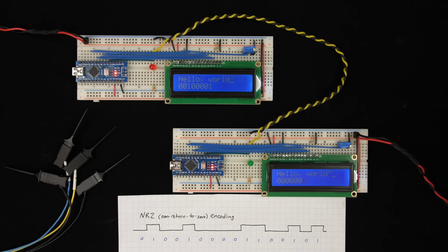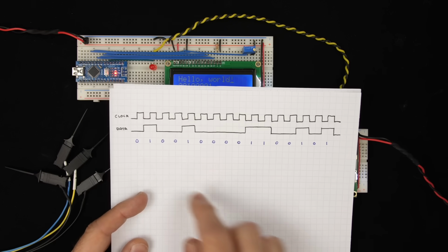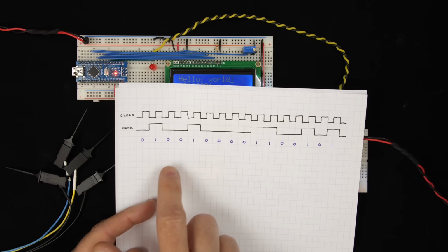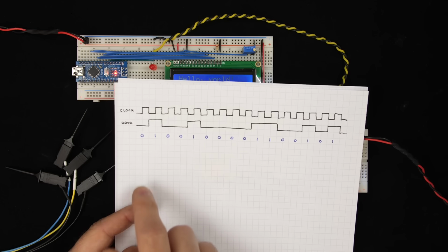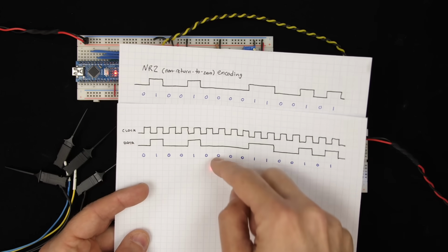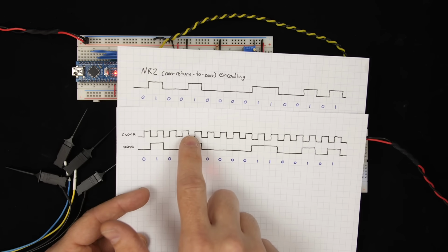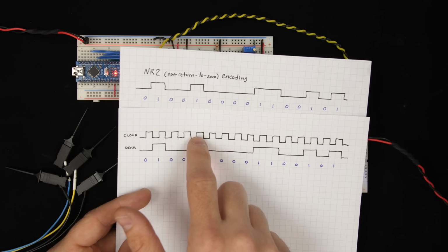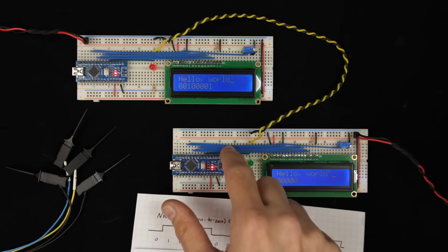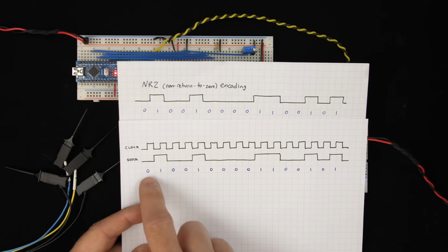completely unreasonable. But what is very easy and very common is to send the data like this, but then also send a clock. So essentially, we'd send two signals that would look something like this. We'd have the data, which looks just like our NRZ encoding. In fact, it's exactly the same. But then we have a second signal that we would send, which would have a clock. And then the clock would just pulse on and off. And then the receiver could then use that clock to figure out when to read the data.